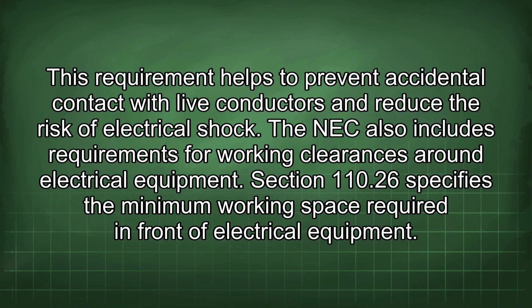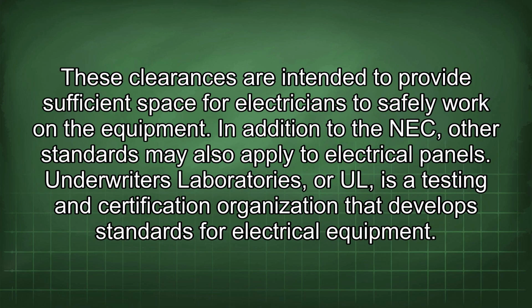The NEC also includes requirements for working clearances around electrical equipment. Section 110.26 specifies the minimum working space required in front of electrical equipment. These clearances are intended to provide sufficient space for electricians to safely work on the equipment.